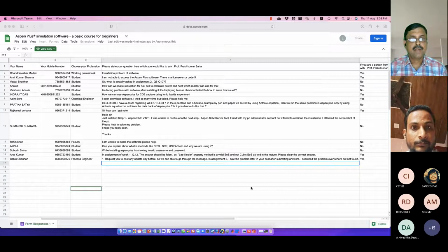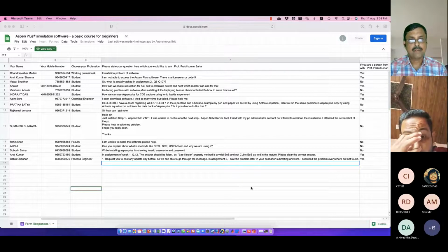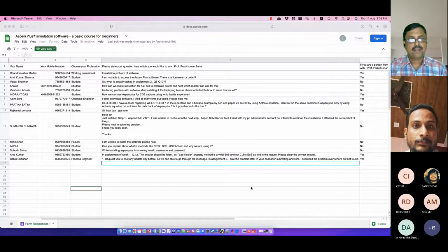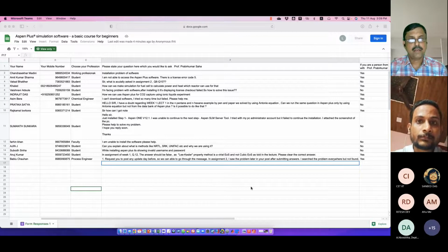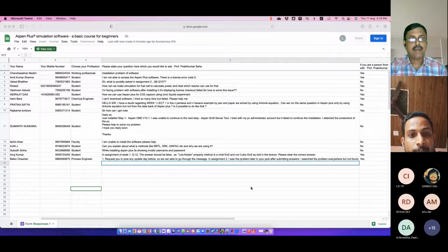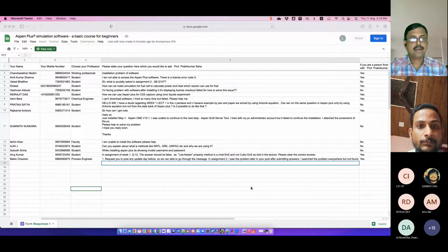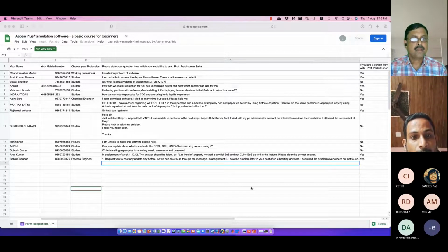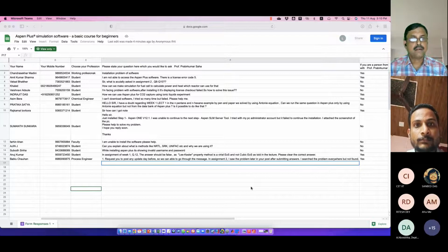But definitely, if it falls under some kind of absorber, as you are saying you want to capture CO2 in ionic liquid, definitely you will use some absorber, right? So you can use absorber model where you can put ionic liquid as liquid and CO2 as gas, and then you can try it. Okay? Absorber model. And I have discussed the absorber model in detail, so you can check.